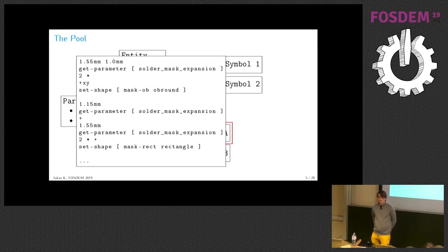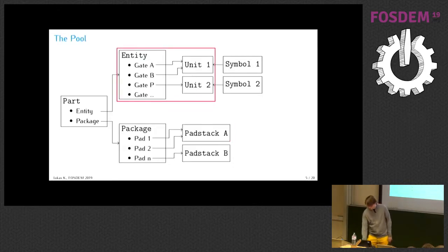So that one feature that the guy mentioned in the KiCad presentation, that's possible in Horizon since pad stacks get parameters from the package, which gets parameters from the board. For example, things like the solder mask expansion or paste mask shrink come from the design rules, and other things are also doable with that method.